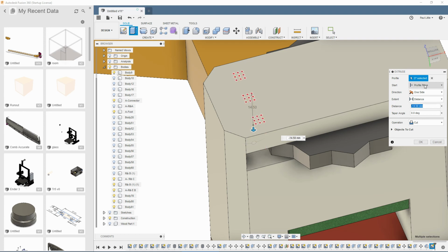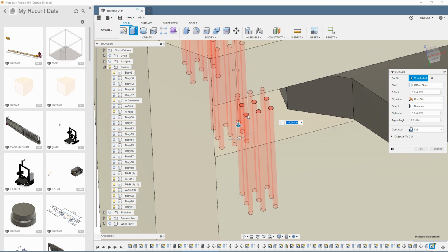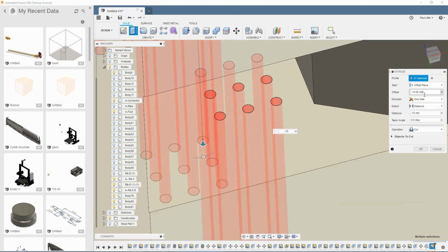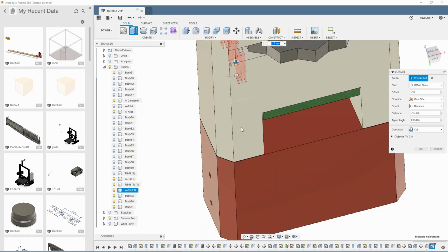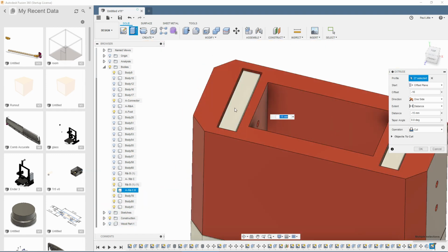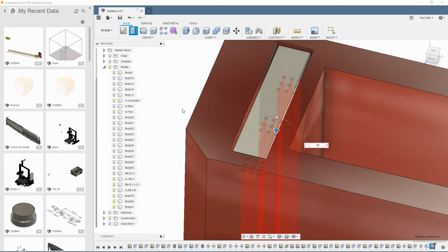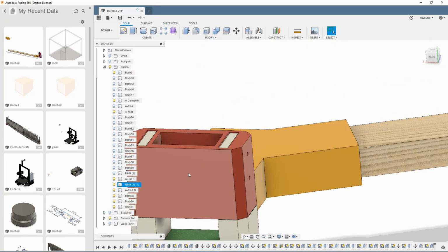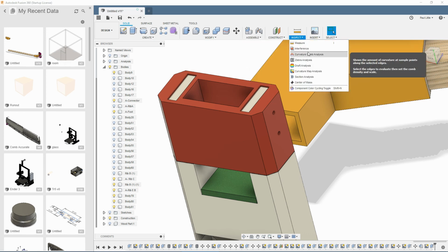So I will copy that number, profile plane and offset plane, and what this is doing is it is starting it right here. Now, I also don't want holes in the bottom of this, so we'll do it as negative 15. Oops, this one needs to be negative 16. So it has about 1.5 millimeters. Next step is it needs to go up here. So I'll select that. Now I don't want it to actually go through the end there, so I'll just take it down some, negative 90 will do it. So that, can't see it, but that is an internal strengthening device, which I guess makes this a twofer for this video.